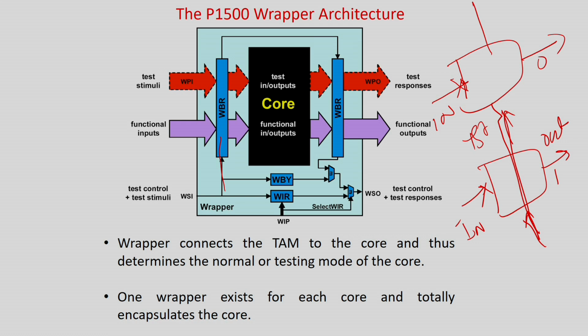But so this is a normal serial mode of doing, just like a scan. So you apply the scan, fill the scan chain, and after the scan chain has been applied, you do the testing. But in normal mode of operation, the scan chain will not be enabled, and direct input will be going over here. So there is a multiplexing arrangement in the boundary register.